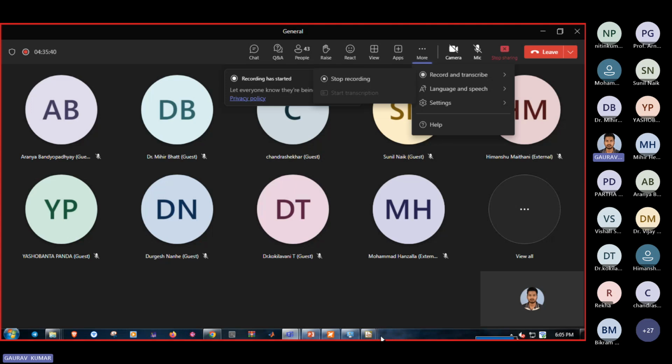So depending upon the voltage range, it can identify the intensity. Let's suppose your color is very dark, so its voltage should be around 3 volt. If it is too low, then it is around 1.5 or 1 volt, like that. So depending upon the output voltage, you can find the intensity of darkness or anything. So first you have to convert it into voltage output. You have to use some transducer so that it converts into a voltage range. You have to find sensors which can convert into output voltage.